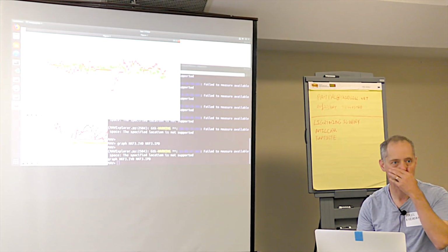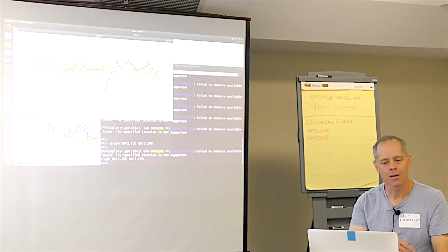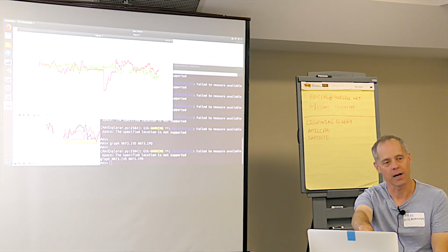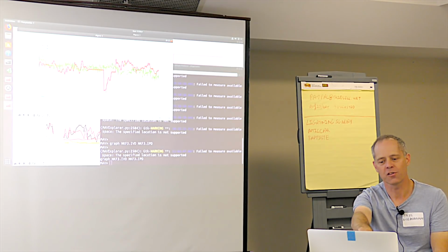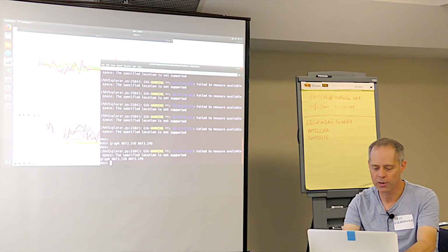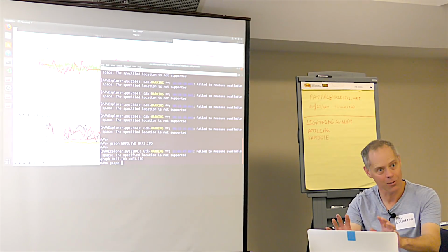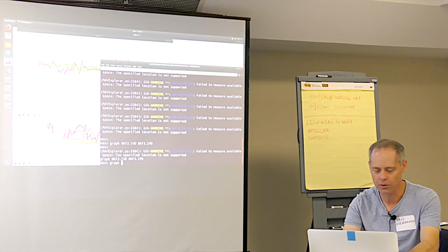Yes, I usually check the GPA message first, which gives you whether the GPS... Well, okay, so this is looking at the output data, right? And this is evidence of a glitch. Now, you can have a look at the GPA because we can graph the GPA, and that's what the GPS reports. But if there's multipath, it doesn't always report a glitch. But sometimes, often it does. So we can look at GPA.